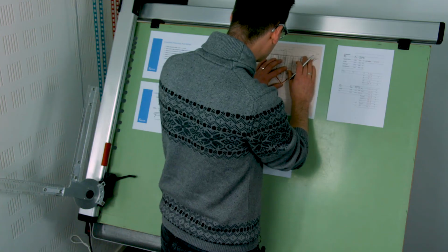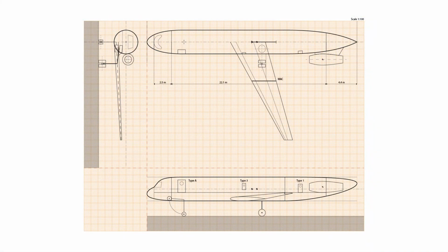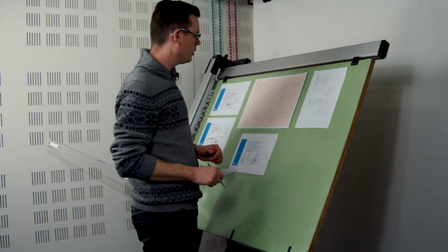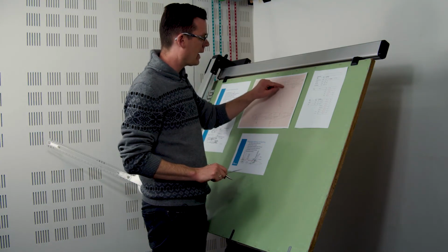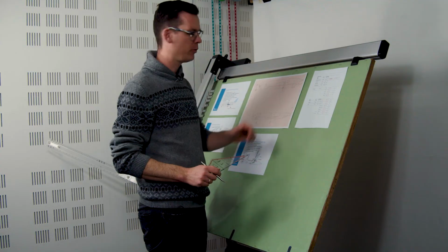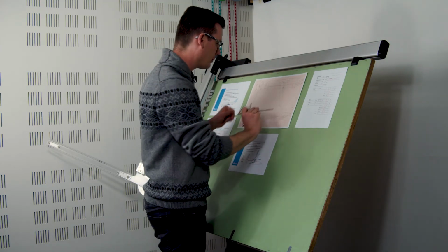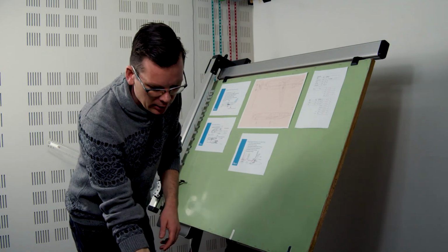So now I'm going to the side of body. I'm also measuring 1.2 meters there, and I'm simply making a straight line until it connects to the trailing edge. So what I've now done is introduce a kink in the trailing edge, and that kink allows you to have behind that auxiliary spar a flap of constant chord. That's going to be your inboard flap. So I've added a kink into the wing section, and I will actually erase